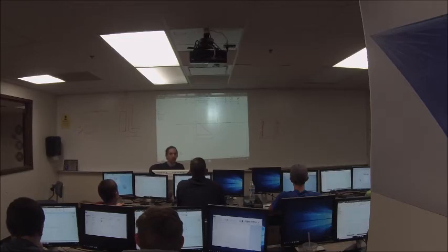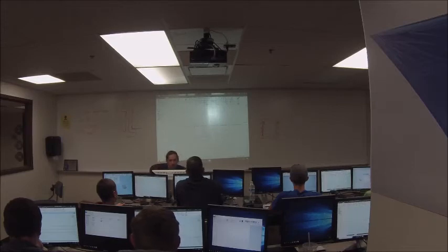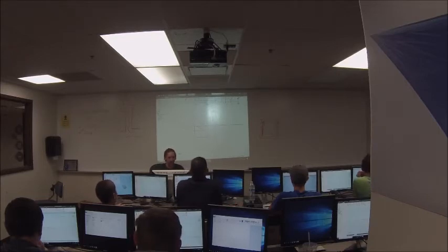That's important. To place a coincident constraint, you can just pick a corner and attach the corner to the origin point. That works. You could use dimensions to attach it to the origin point and just say I wanted an inch away from the origin point, right? You could do that too. But a real easy way to do it is just click and drag a point and snap it to another point, and it'll automatically place a coincident constraint for you.